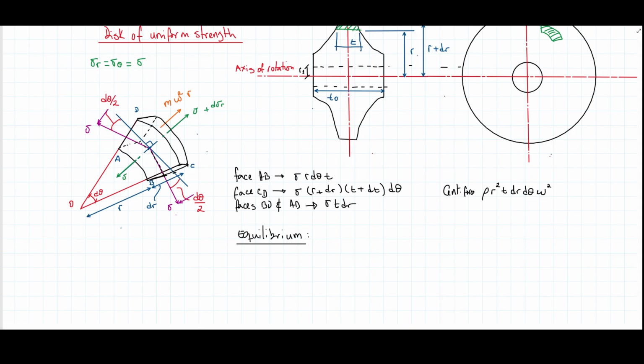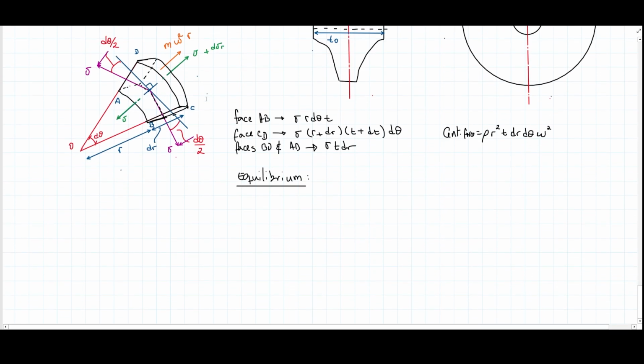Centrifugal force. Then inwards equals outward forces, and we're going to get that inward forces are going to be AB and BD, AD. So those are this one here, T plus 2 times, again, the same deal with these two forces here. So they're going to be sigma T dr sine of the differential of the angle here. And it's going to be equal to what? Well, to the outer force CD here. Let me write it down, this one here.